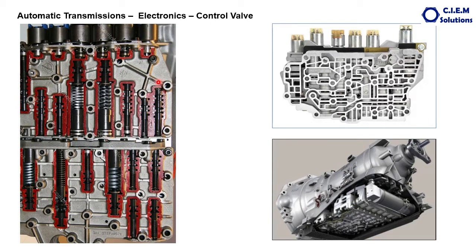Because the main purpose of adding solenoids for the movement of the spools is to have more precise shifting of these valves and smoother shifting of the gears, because the actuation time from the solenoids will be in milliseconds, which is more precise and faster. So the smoothness in the shifting of the transmission gears is increased, so that the life of the components also increases.